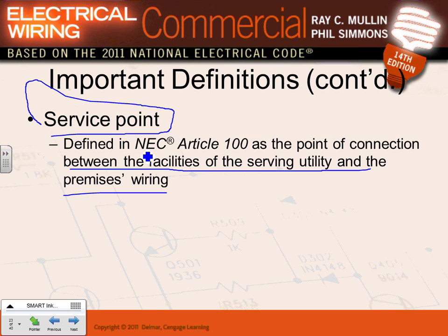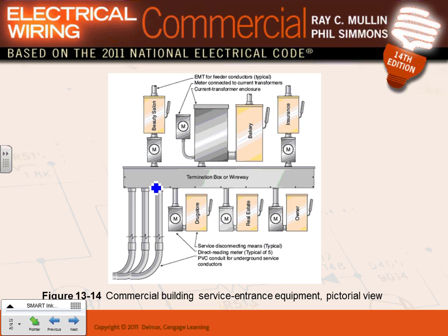Okay, here's how the building that we have. This is for the project inside your building, guys. They brought the service conductors into a gutter. Because these are multi-tenant buildings, the building that they have in this project is not single tenant, it's multi-tenant. Typically what they do, guys, is they bring the phases here and they meter them, right? And then they disconnect them.